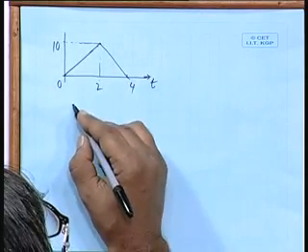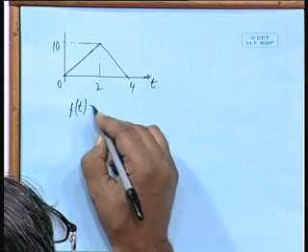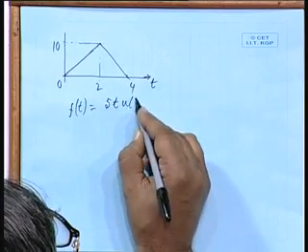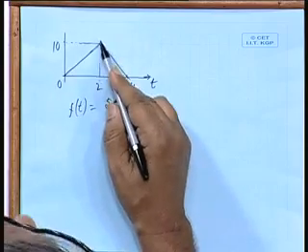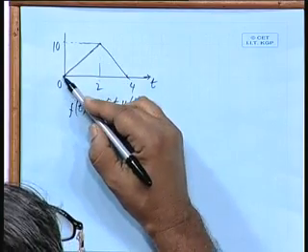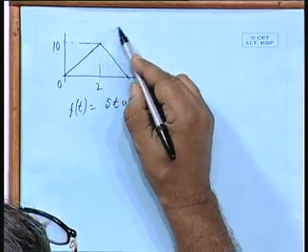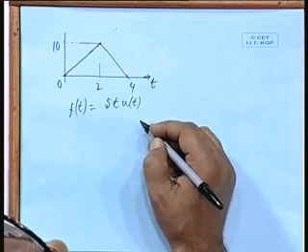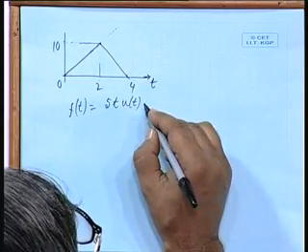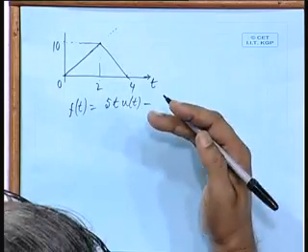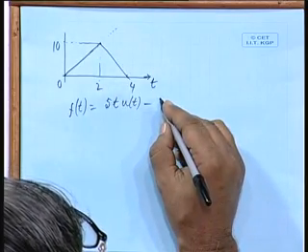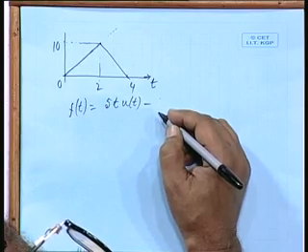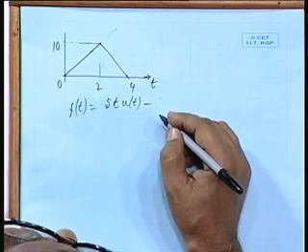So, f(t) will be 5t u(t), agreed, that will be taking it along this line, but at t equal to 2 what do I give? A decrement. So, now tell me what should be this? Minus 5(t minus 2) u(t minus 2),